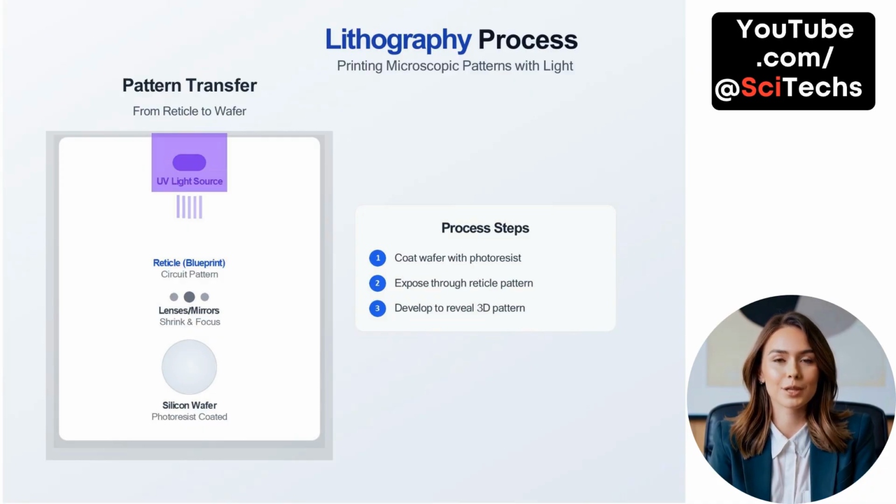Finally, the wafer undergoes a development process, where the exposed or unexposed areas of photoresist are removed, depending on whether a positive or negative resist is used. The result is a 3D relief pattern that defines the layout for subsequent processing steps.